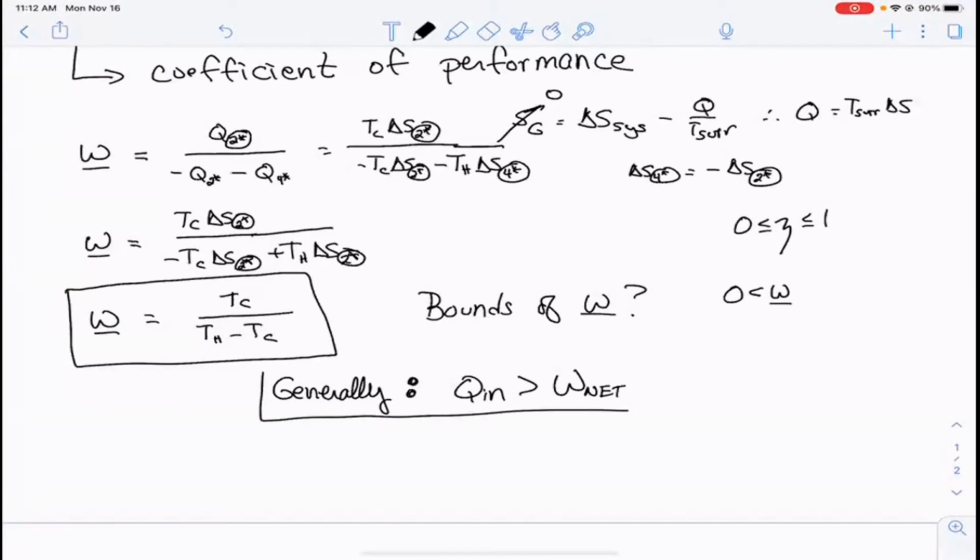But this is like weird thing number 2 for refrigeration cycles, right? The first one was just getting your head wrapped around the fact that heat enters the system at the low temperature. And the second one is that you're often able to extract more heat than the work that you put in, which kind of makes it feel like you're getting a free lunch, but that is not the case. And so that's sort of weird thing about refrigeration cycles, number 2.